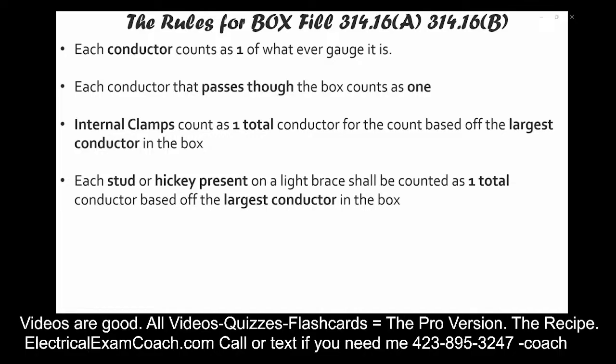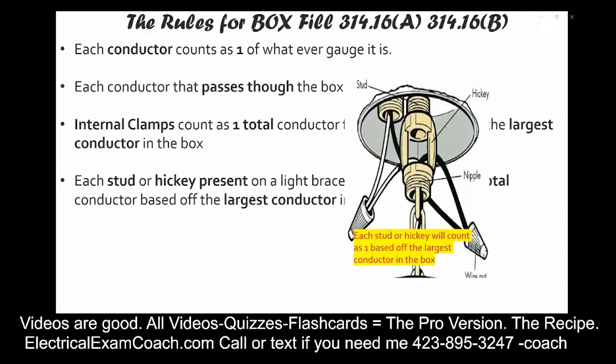Now, these are really old words, probably from the 30s if I had to imagine, but they still use them on examinations today. And this is what we're talking about. Imagine that we're hanging a chandelier. This would be a nipple, but they're calling this the stud and this a hickey. And they still use this terminology on exams today, so you definitely need to understand. In this picture, the stud would count as one of whatever gauge was the largest in the box, and the hickey would count as one of whatever gauge was the largest in the box. And we're going to do lots of practice, so don't worry about it.